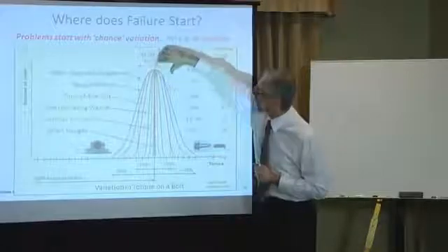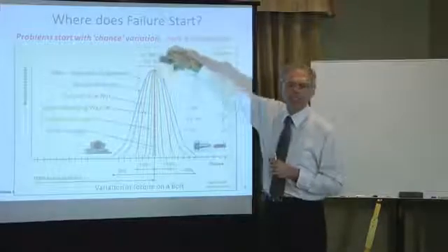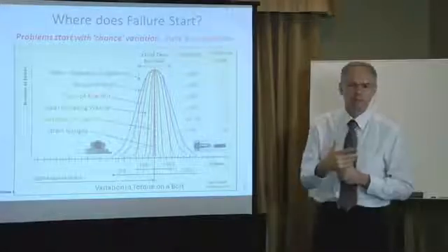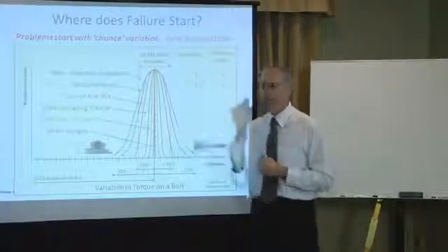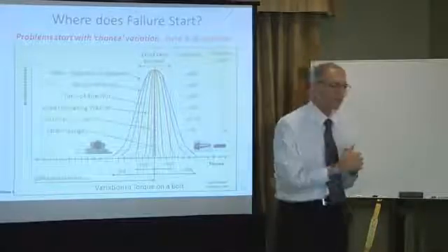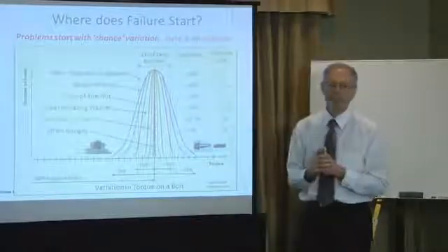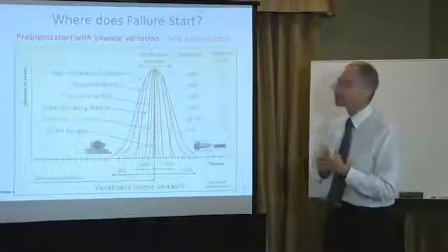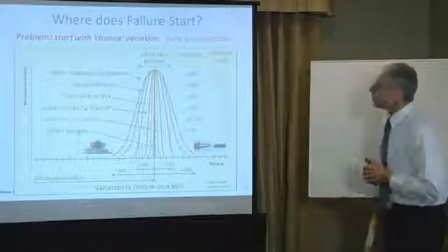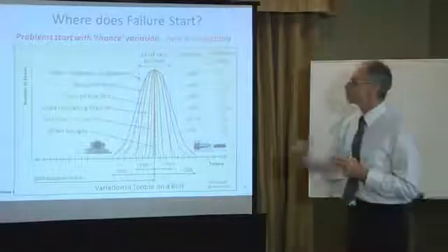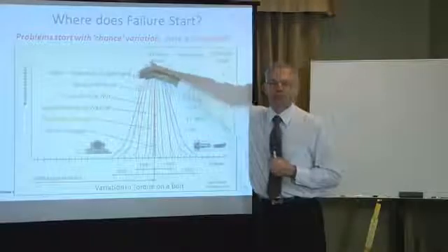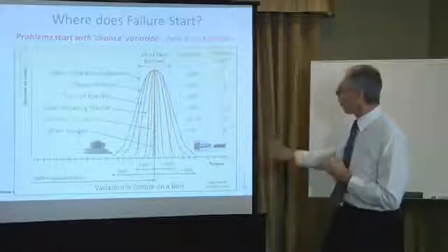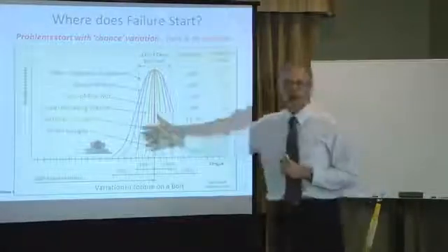Mostly, what is it, 68% is in that zone there. So most times it's going to be fine. And that's the trick. We look at that and say, well, that one's okay, no troubles, no troubles, no troubles. And so we think that works fine, except the outliers are the problems. And there are outliers built into this as part of its use. As an engineer, I was taught doing up things by hand is fine. As a tradesman, I was taught doing up things by hand is fine. Well, it is fine if you don't mind things being occasionally broken or occasionally loose.